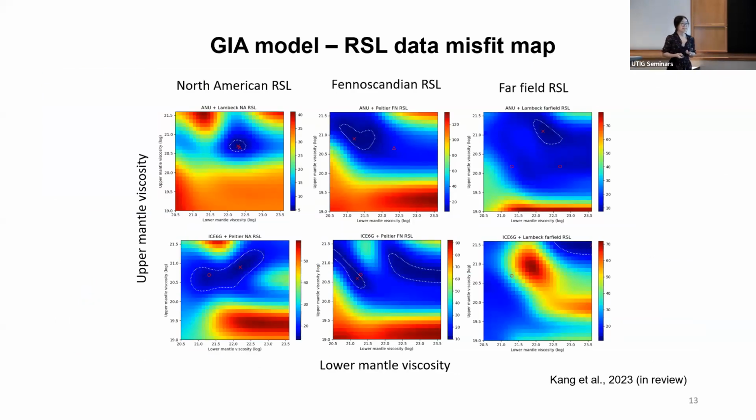And then we have the data, also we have the ice model, and then we can use this input and output to test the GIA, the Earth rheology as a black box. We just twist it. For example, here I use a two-layered model. We have lithosphere here, but as constant. And we vary the upper mantle viscosity and lower mantle viscosity, adjusting these two parameters to see which grid will best fit one particular relative sea level data given by one particular ice model.